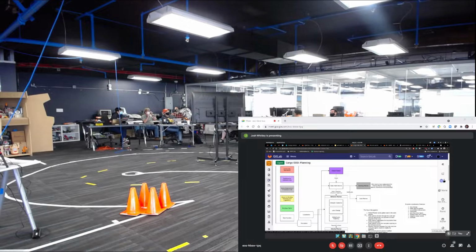So for the new version, we have created a static path planner, which will call the docking planner, which is our replacement for the parking, and the lane planner, depending on the segments of the route we're talking about. And then that will pass it on to the behavior planner. The behavior planner will do real-time obstacle avoidance on the subsection of the route that we're looking at ahead of us, rather than on the entire route.